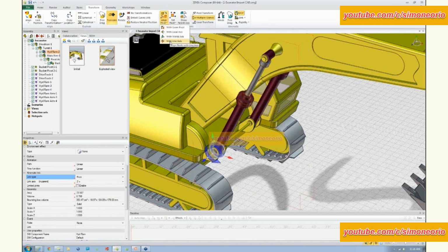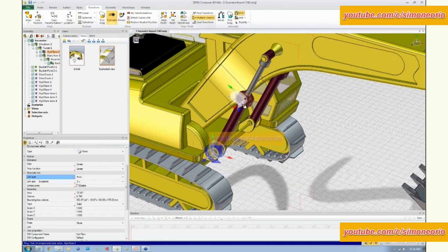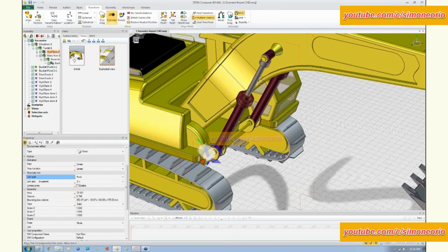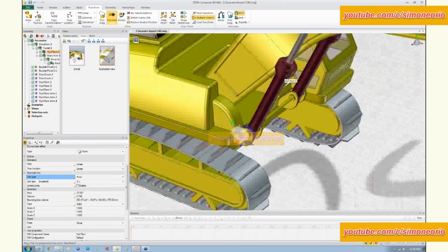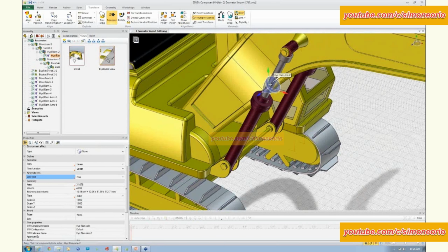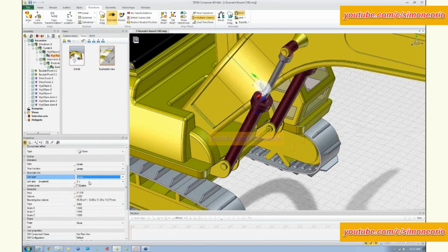So I'm going to align it with a line axis and have it align with the actuator itself. The parent axis is still oriented with relation to the world, so it's still rotating, pivoting about the point that I want. But what I'm going to do next is move on to the pivot attached to the slider part of the mechanism, and I can say align this pivot with a given pivot and pick its parent, and now it's aligned with the parent pivot. And then I can say this is a linear pivot and moves along the z direction.